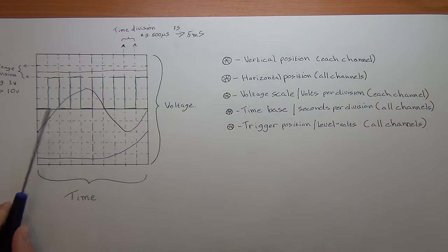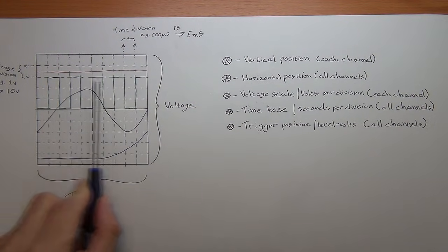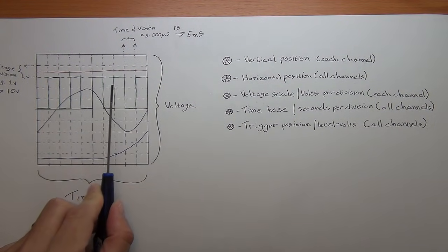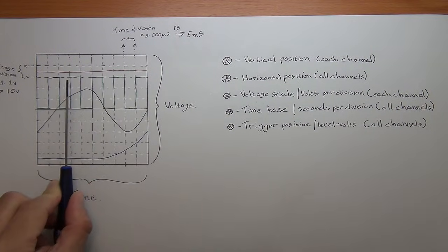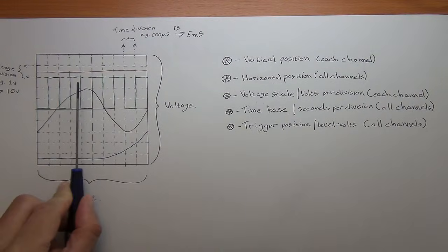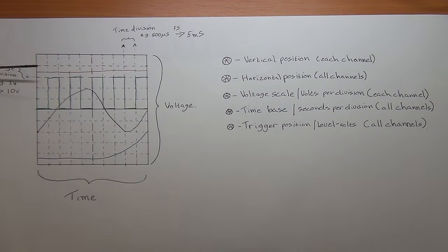Your signal might not necessarily be a clean one displayed in the same position of your display the whole time, and that can be rather difficult to evaluate if you want to keep it live and it's jutting around and moving around. So what your trigger does is you set a level at which you want your scope to capture that signal. It's adjusted down on your voltage division. You move your trigger down to the middle point of your signal.